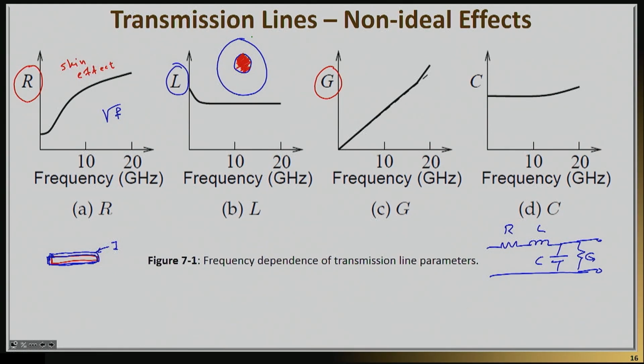Now I don't. And so that means the inductance will become lower. Similarly, the capacitance per unit length has a weak dependence because the dielectric of the medium, epsilon r, also changes with frequency. So lots of things can go wrong as you imagine shifting things over frequency. And that's, by the way, one of the reasons why wideband circuits are harder than narrowband circuits.